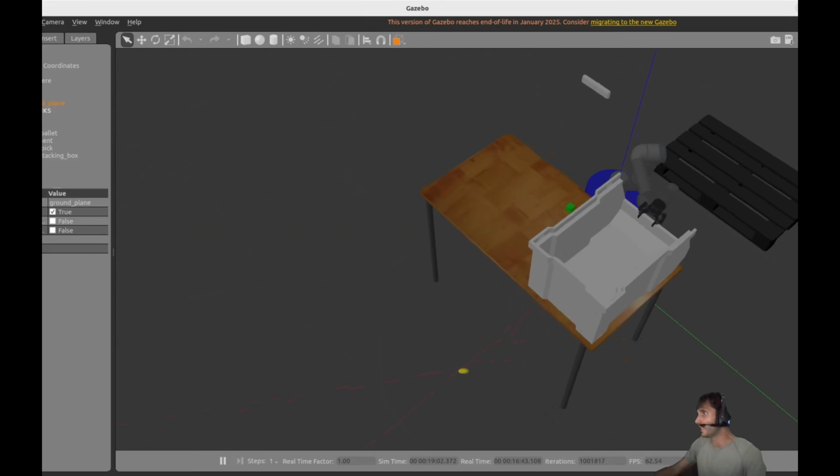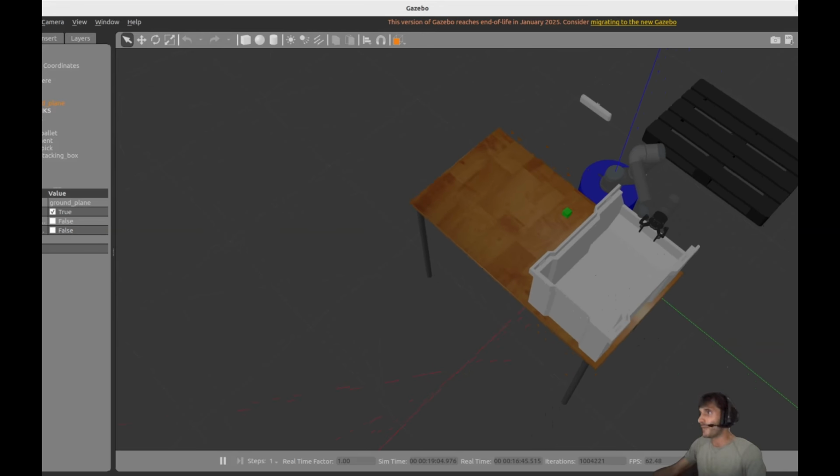Okay, so basically if we were able to pick the object, then we just needed to ask the robot to go to that position, and then the camera, thanks to the fact that it's publishing a message of type camera points, MoveIt translates this topic into an Octomap, and this allows you to run by default an obstacle avoidance algorithm.